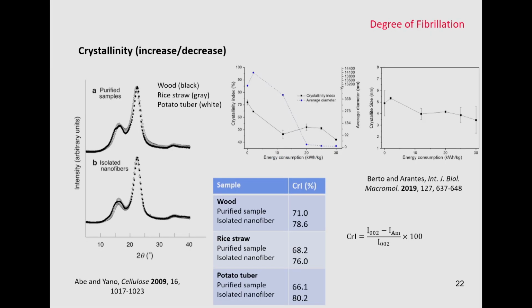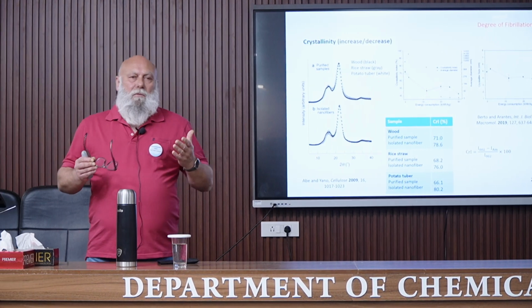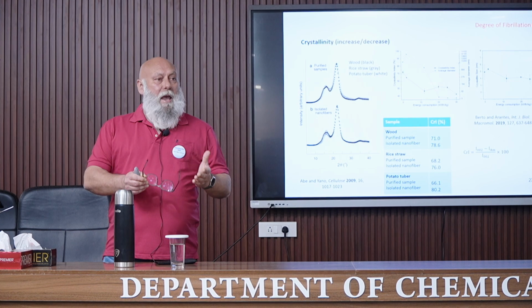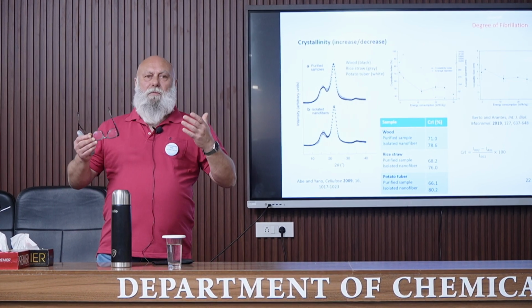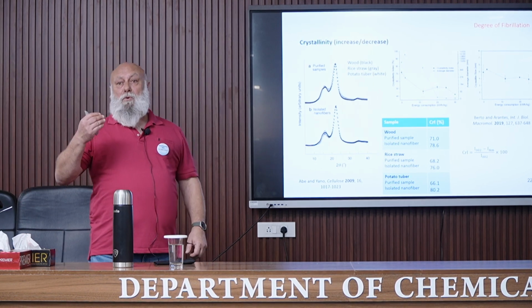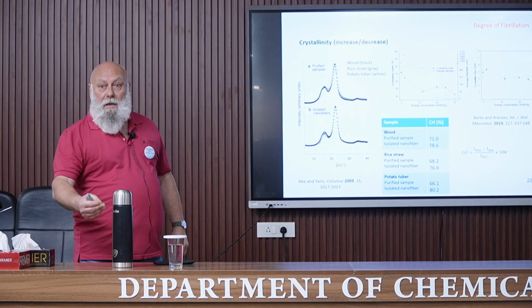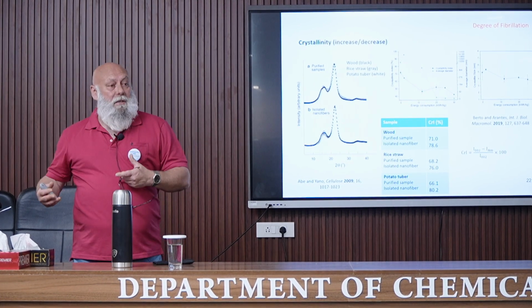Crystallinity. Sometimes it increases, sometimes it decreases. What is the reason for this? We can imagine that during the mechanical treatment, we can easily break the amorphous domain, meaning that the degree of crystallinity should increase. But of course, some crystalline domains are also damaged during this mechanical treatment, meaning that the degree of crystallinity can also decrease.